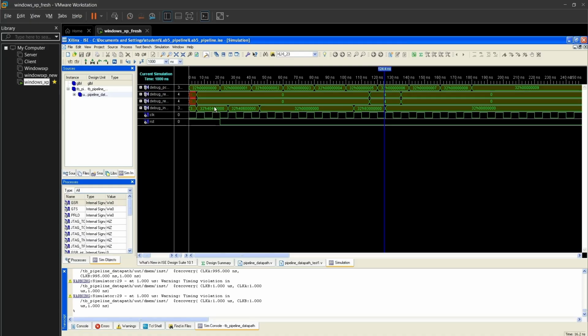I can see the instruction based upon the IMM we have given, and we are using the COE file, which seems perfect for the IMM as well. This works for input PC instructions as well as the automatic PC, which is the actual behavior of a closed processor.